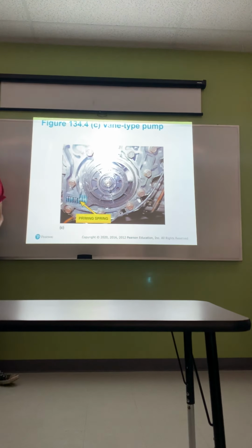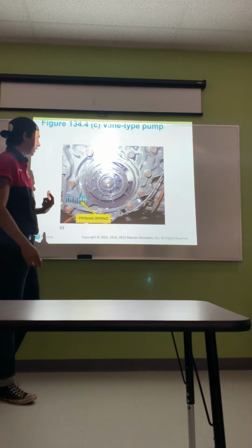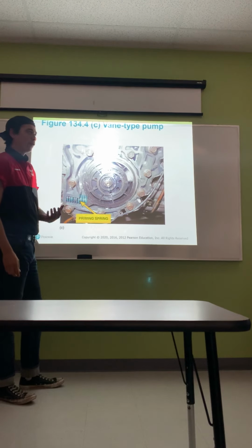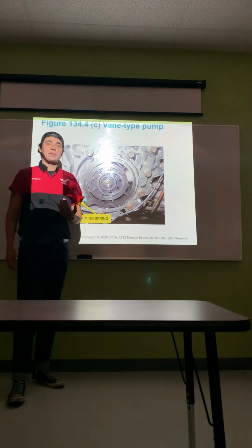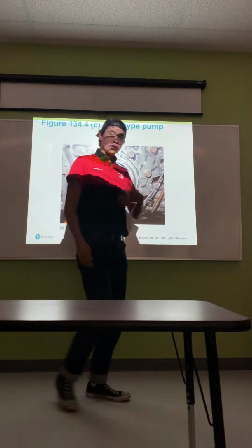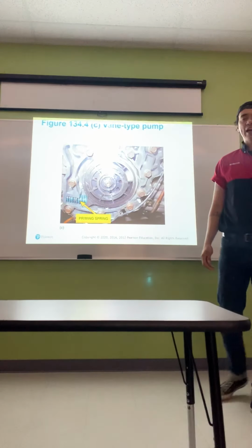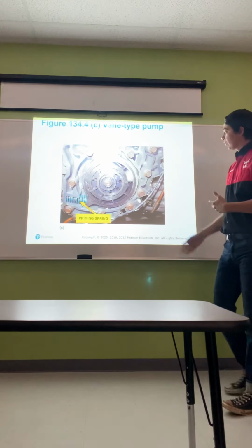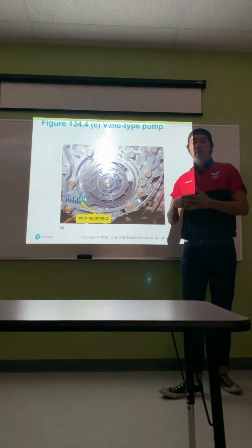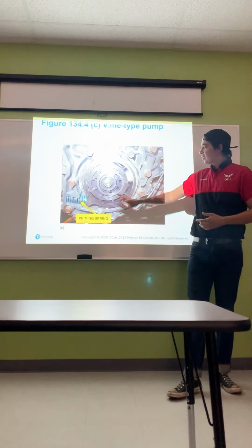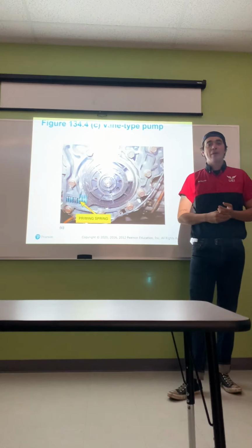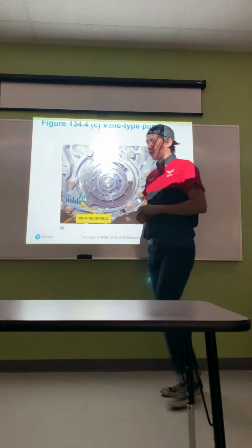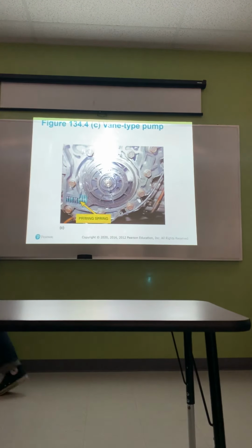In order for it to maintain pressure and not burn out the pump, you need to have fluid flowing through this pump constantly. That's why if you have low transmission fluid, or say no transmission fluid, when you first initially start the car, you could run into the possibility of burning up that pump. So you want to make sure that you do have fluid in the transmission before you start the vehicle.